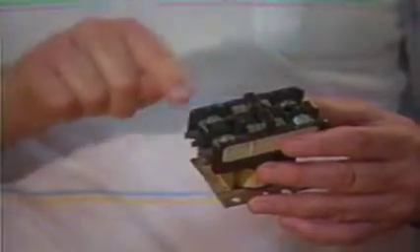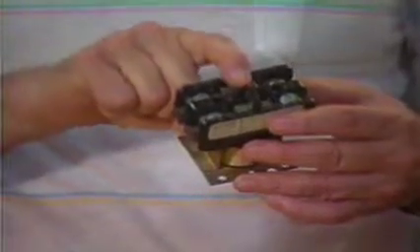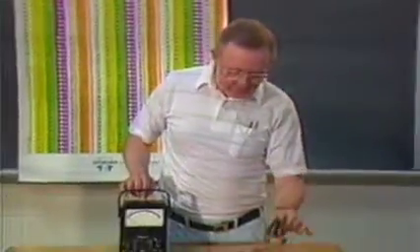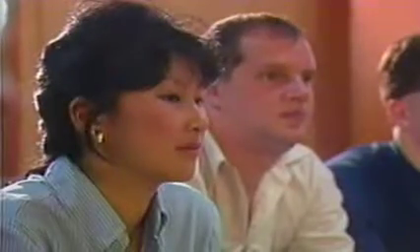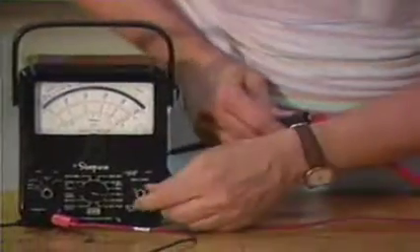It has one circuit through the set of contacts, or sets of contacts, that passes power. Power comes in, power is supposed to go out. This circuit, whenever the coil is energized, should close the set of contacts. The coil circuit is actually considered a load circuit. Now what we're going to do is we're going to test this relay out using the VOM. First thing I'm going to do is zero the meter.